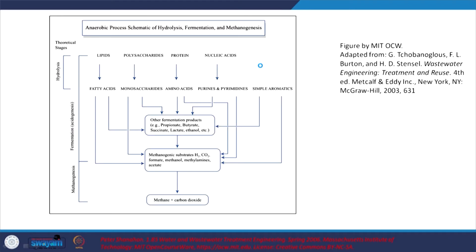There are different stages here, and note that my sludge has all these relatively complex organic matter. Complex stuff, well, I can't digest, which is typically why I am going to cook it. It is not the same analogy, but similarly for the microbes too, remarkably complex organics, they can't degrade or use them well enough. So, first they have to be changed into forms that are relatively more soluble and also relatively easily usable by the relevant microbes as the substrate.